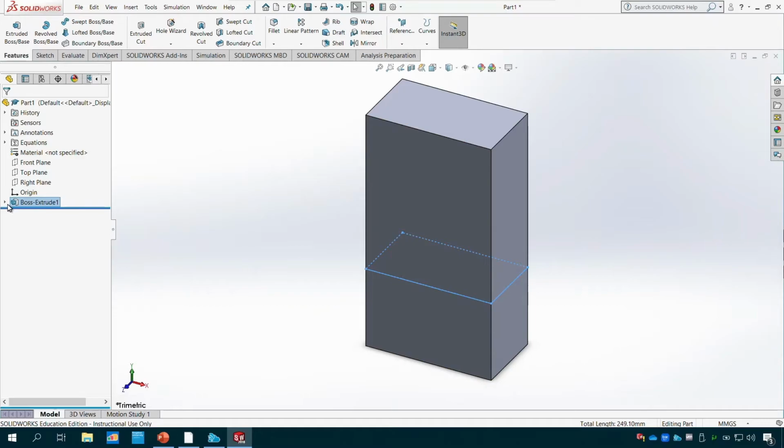You can see every single one of these 3D models comes out of a sketch, and this is why the software puts them like that, so it'll be easier for you to find out what sketch is driving that extrude. Anything you want to edit, you can do the same way as with a sketch.